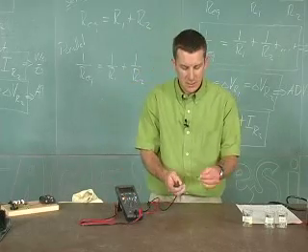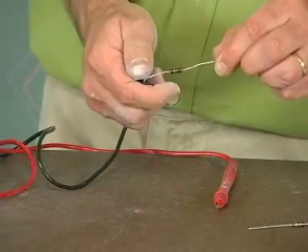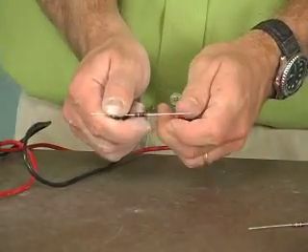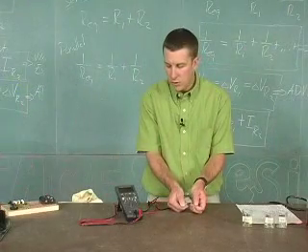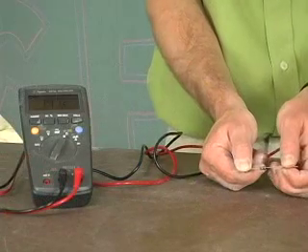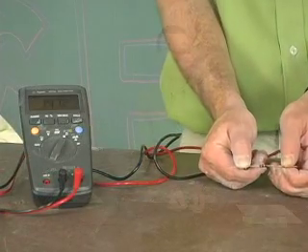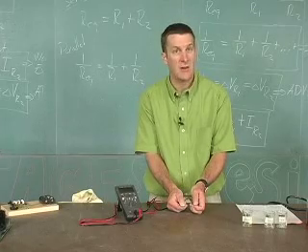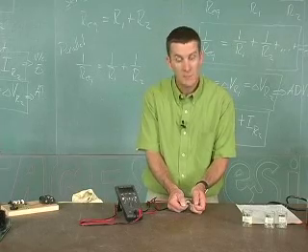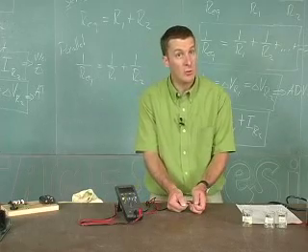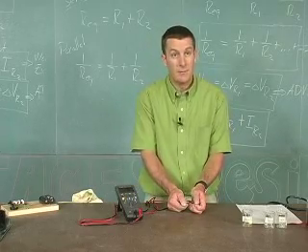To measure resistance, you can take a simple resistor and put it between the two probes. If you do, you can see on the multimeter that we're getting a reading of about 147.2 ohms. Well, this resistor, this device, is rated at 150 ohms. So it's not reading exactly, but we are able to get the right idea.